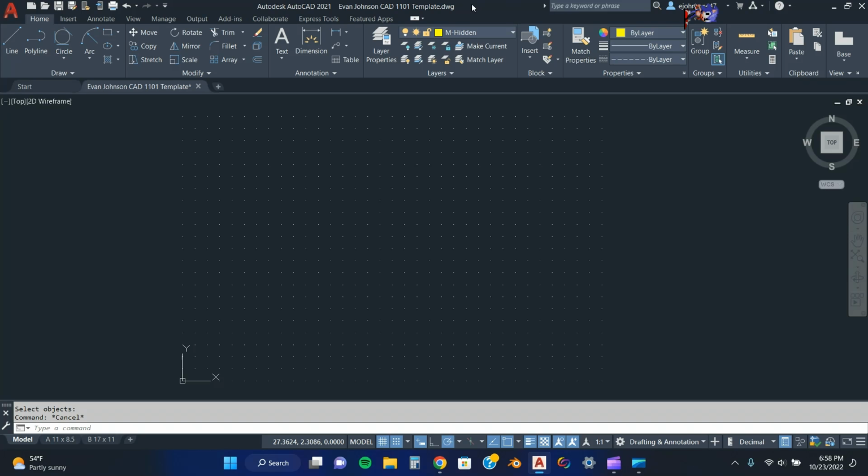All right, so today we are checking out the line tool. Might seem pretty simple, but there's actually quite a bit to it, and it's kind of the foundation to a lot of other drawings that you'll do. So with our line tool, we can choose it from up here, or we can also type in LIN, and then it comes to the top of our choices, enter into it.